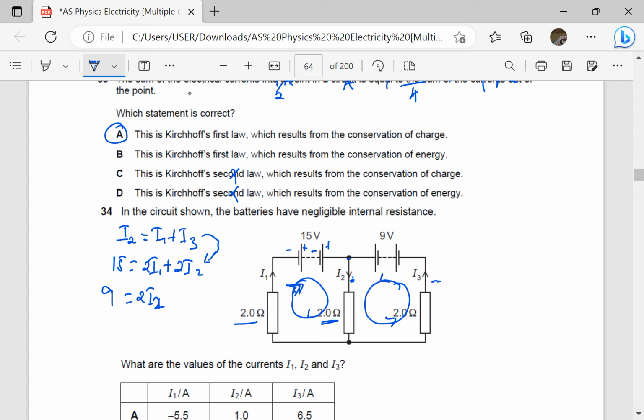And this current is in the same direction also as the loop, so this is also going to be plus 2 times I3. So because here I have I2 and I3, I'm automatically going to eliminate I1 in the first equation. When I remove it in that equation, I have that 15 is equal to 2 into where there is I1, I'm putting I2 minus I3.